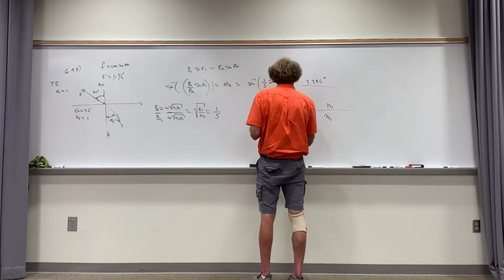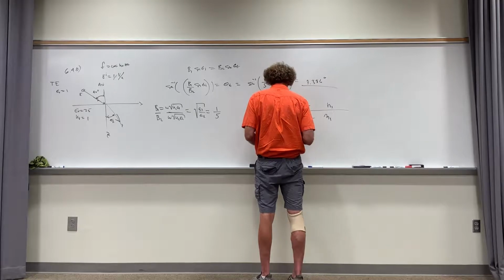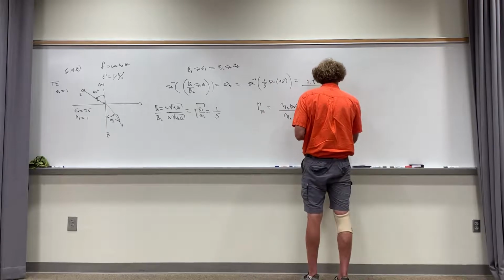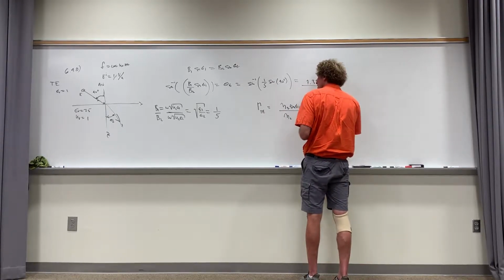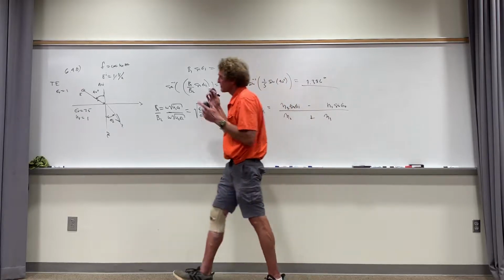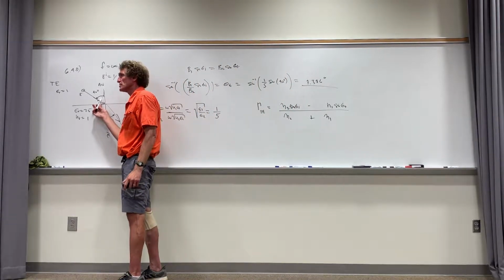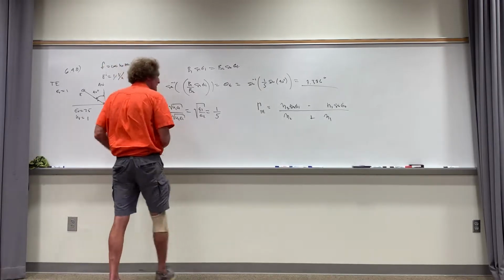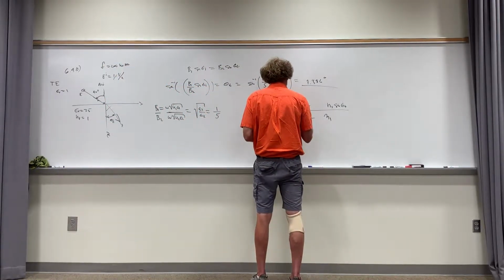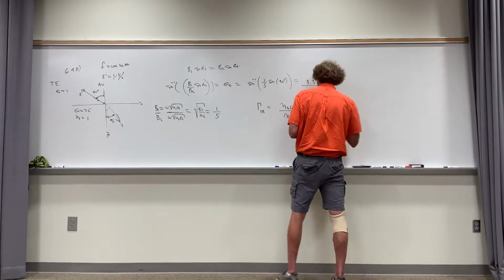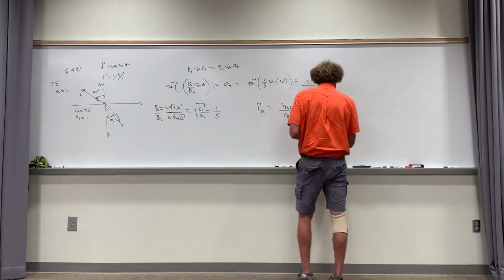And then I know for TE, it's eta 2 times the sine of theta, cosine, right? No, I'm sorry. Sine, in this case, sine of theta incidence, and this is going to be sine of theta transmitted. This is, wait a second. Our book uses this; I teach radar too. The angle we're using is with respect to the normal, right? Isn't that right? It has to do with this angle and this angle. That means these are cosines, sorry. So it's cosine of theta incident here, and this is cosine of theta transmitted. This is cosine of theta incident. This is cosine of theta transmitted.